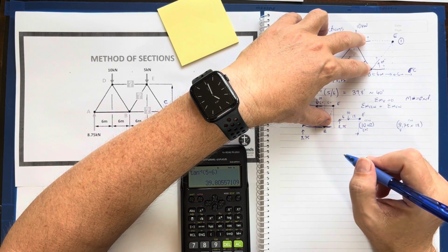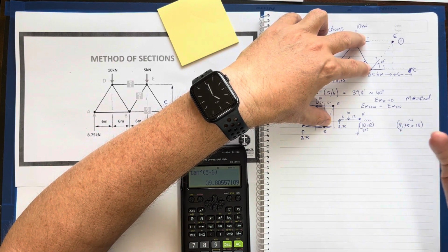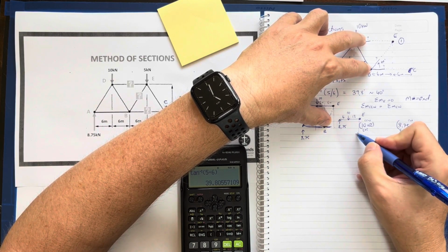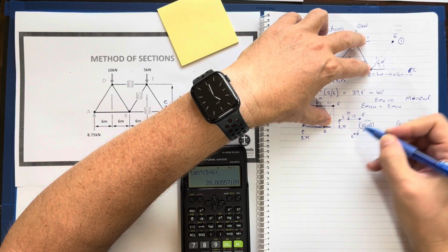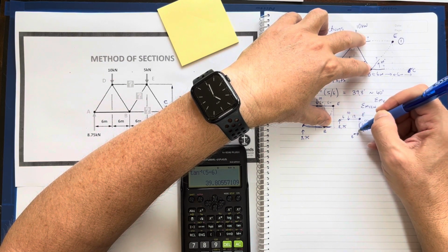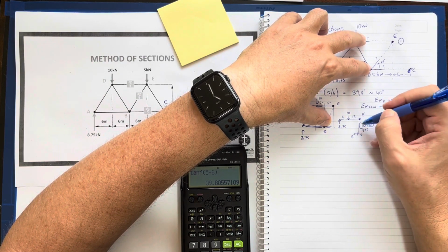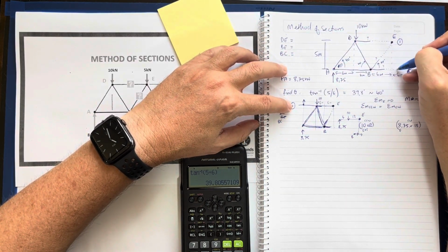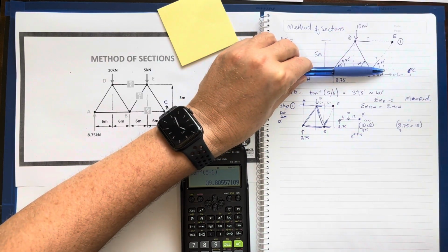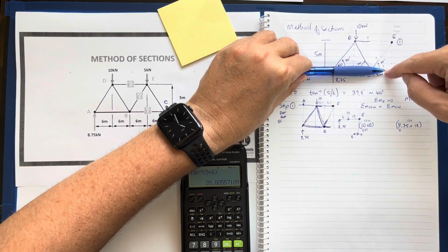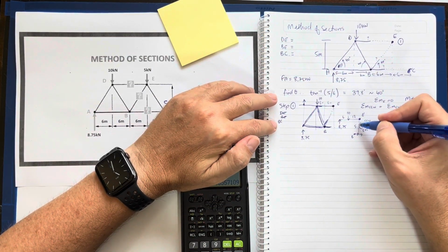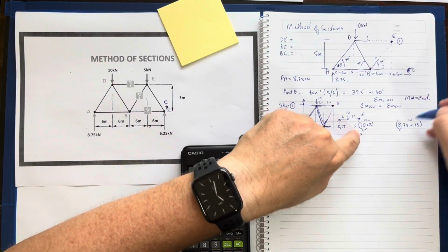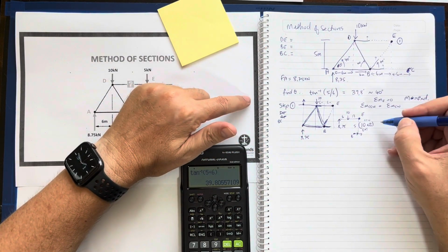I don't know what its internal force is, compression or tension, so I assume it's positive, I assume it's in tension, and therefore the arrow is going away from the joint at B. But it is perpendicularly that far away, 5 meters, pushing in that direction. This is when you're going to have a bit more lateral thinking, and it's going to make it go counterclockwise.